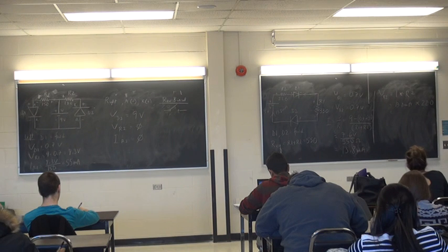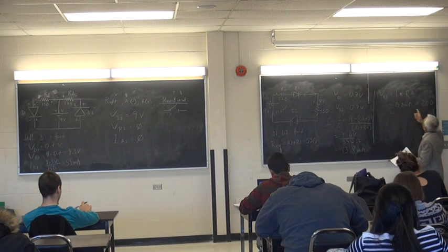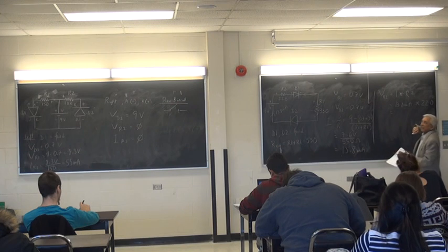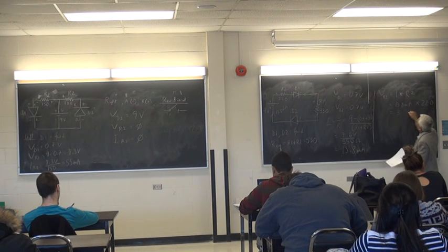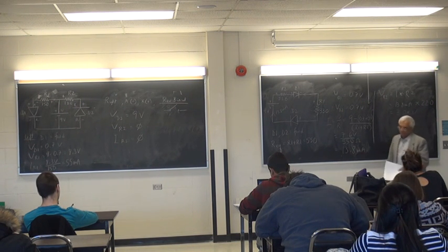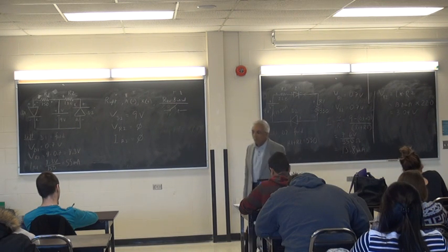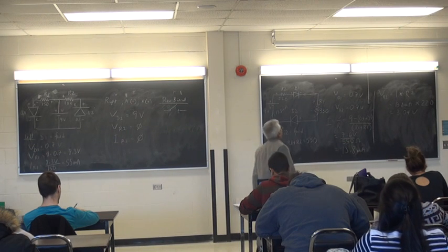Okay. So now that I know that the current in the circuit is 13.8 milliamps, I can find the voltages at R1 and R2, because that is 13.8 times 220 for R2, 13.8 times 330 for R1. Voltage is I times R. So voltage at R2, I times R2. 13.8 times 220. How much? Milli times ohms is millivolts, right? So you can convert it to volts. 3.04 volts. If you take that milliamps and multiply by ohms, you would get millivolts. Then you convert it to volts.